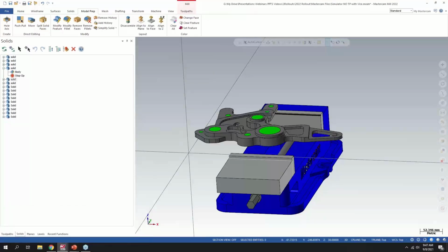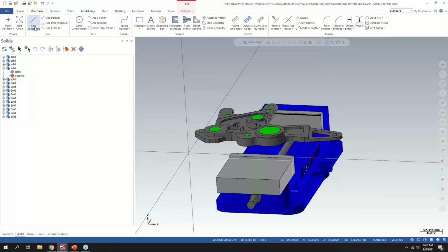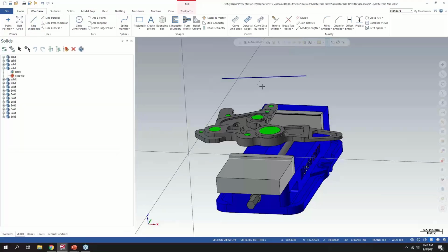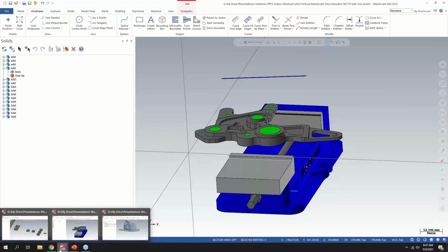And yeah, we had a question about, did I use model prep to modify the wireframe? No, you just have to double click the wireframe entity. So if I have any wireframe on the screen, once it's created, I just have to double click on it to get into the edit command of the wireframe. I was slightly confused on that at first. I was looking for the command in the ribbon bar, somewhere under my right click menu, but nope, you just have to double click it to get into modifying wireframe directly.